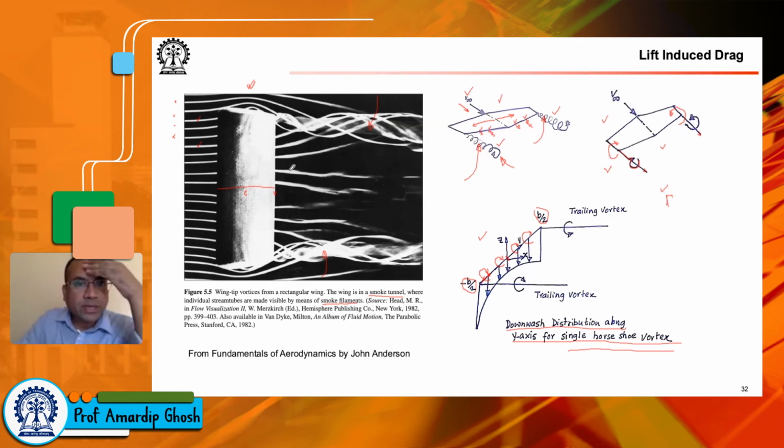So once again, on the top left, you see an experimental verification of these counter-rotating vortices shed from the wingtips. Given the direction of this vortex motion, you can create the direction of the vortex filament, and the strength of the vortex filament will be such that it matches the strength of these contrails. Strength meaning the circulation. I have a slide that revisits what circulation is, but by now you should know that circulation is defined as V dot dl over a closed path around which we are interested in finding the circulation. So that's in terms of velocity and the path.